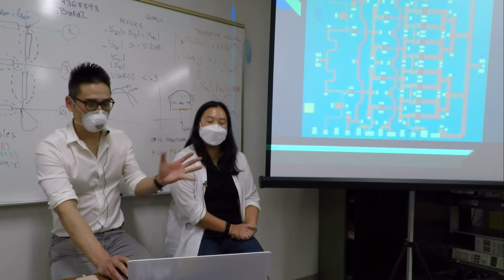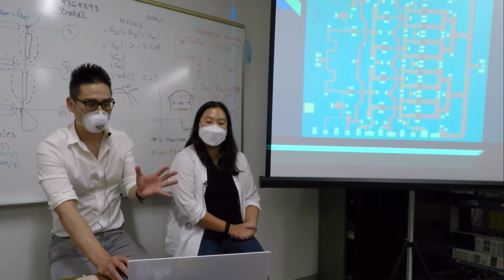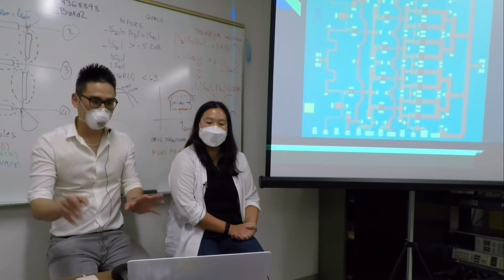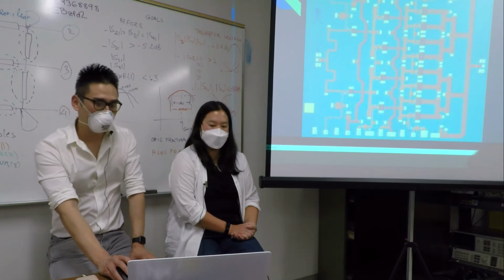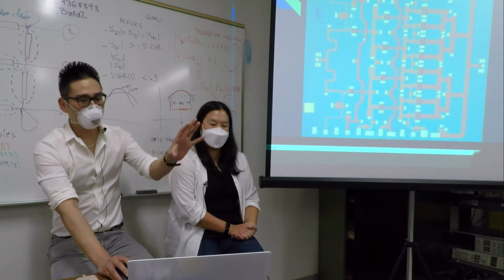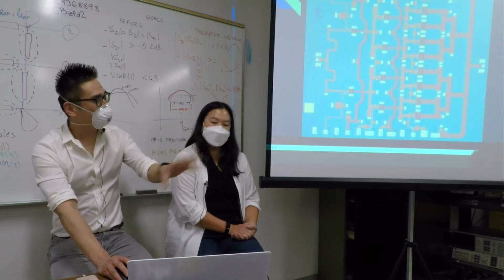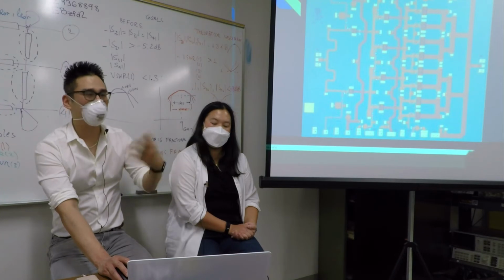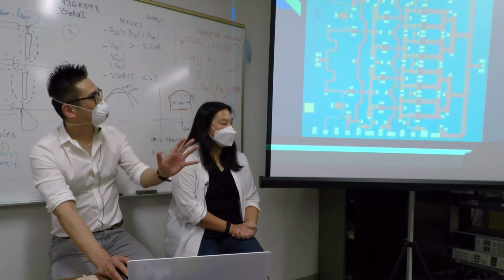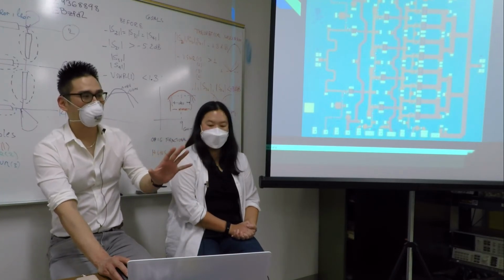Claudia brought up a good point in talking about models. So I go into ADS and now I slap in this icon, an icon on the page that's supposed to represent a transistor. If that were taken as a given fact, then we could easily produce a predictable design. But the truth is that the actual physical device rarely matches exactly with the model.